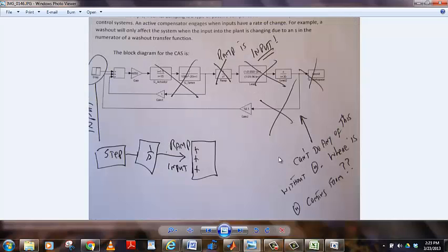Now I realize that this test was time sensitive, but let's look at what these block diagrams mean. In the first case, for this particular one, we have a step input with the ramp somehow occurring over here. I hope you see that the way to implement a ramp input is either to put a 1 over s right after the step, so you have a step going to 1 over s, a ramp input, or to select a ramp input from the options available to you in Simulink.